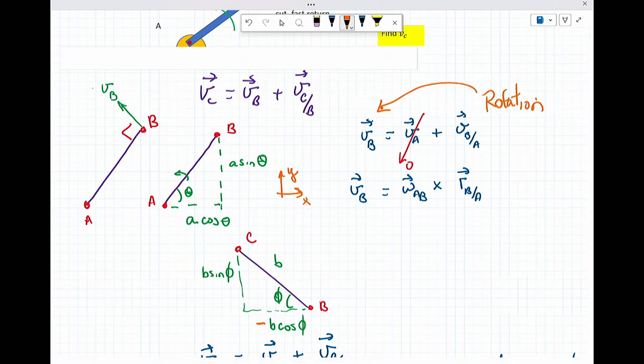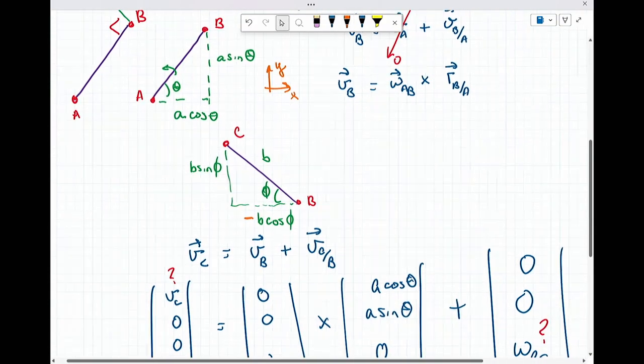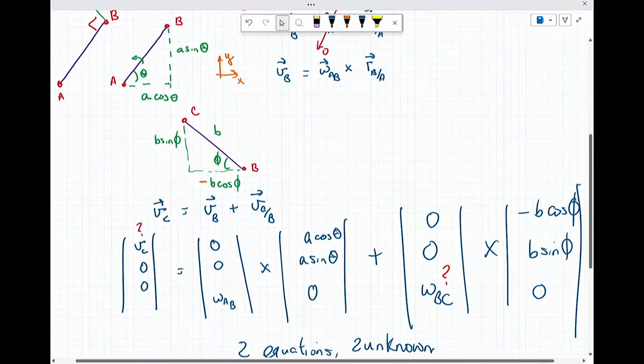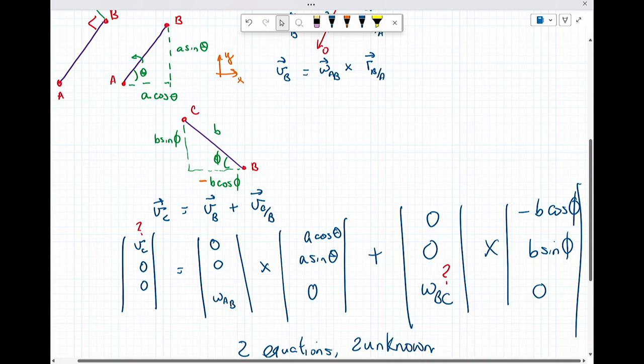And once I know the velocity of point B on the link AB, I know what the velocity of B is on the link BC. When we calculated the final solution, I also knew that velocity of C is translating. So it's moving in the i direction. It's plus or minus, but it's only limited to that.